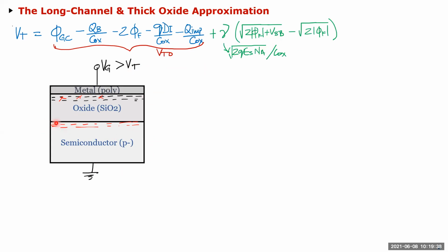If any side of the channel is at a different potential compared to the substrate, then your depletion layer actually changes here. And we calculated that depletion layer. What is the extra voltage needed to accommodate that depletion layer? It turned out to be this function here, which is essentially dependent on the acceptor concentration of this substrate over here. So this is the VT.